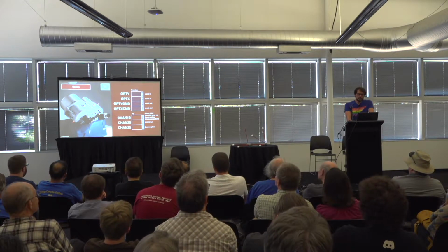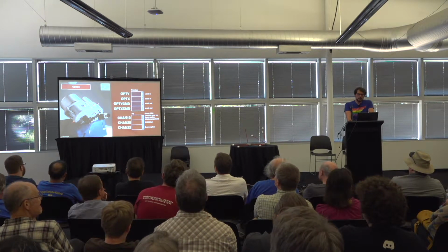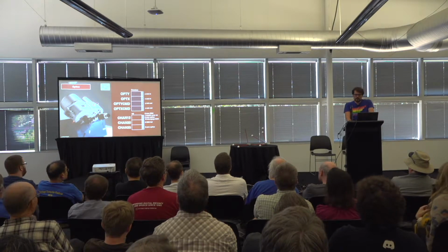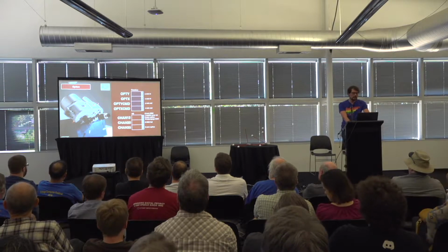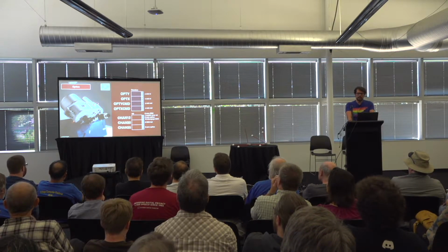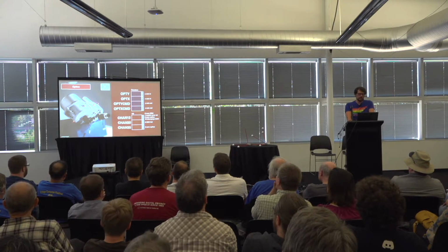On the command module, the optics are used to measure the relative position to celestial objects. The computer uses the OPT-CMD counters to move the optics to point toward the general direction of a star, and will read in the astronaut's fine-tuning through the OPT counters.